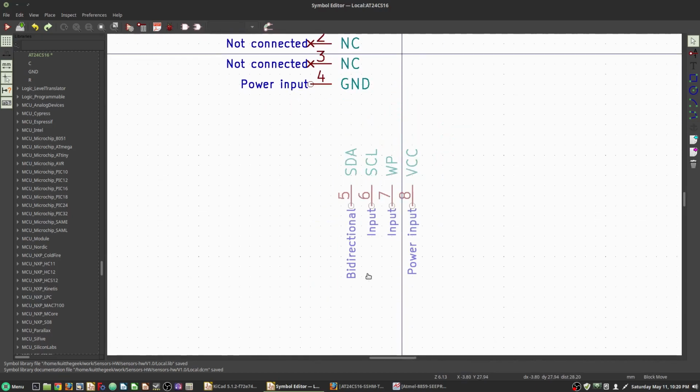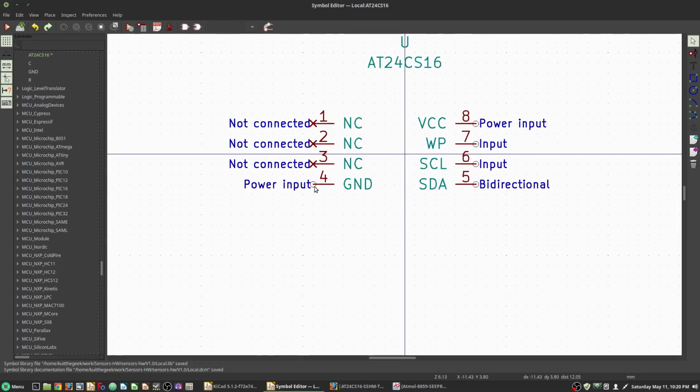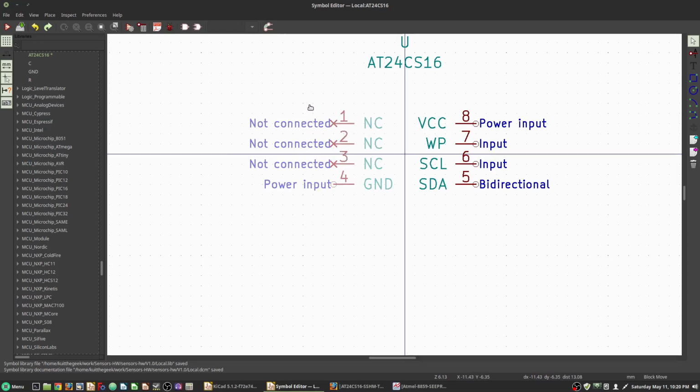Now, let's grab these. We can rotate that by clicking R. I generally like to make sure that the pins are the same distance from the center. So if you hold the mouse over that center pin, you could look down in this area over here to see the dx, the dy, and the distance, as well as the relative position points. And so this is going to be 8.9, and this is 11.43. So these we can move over just a little bit more, probably about to there. Check again, that's 8.9. Okay.